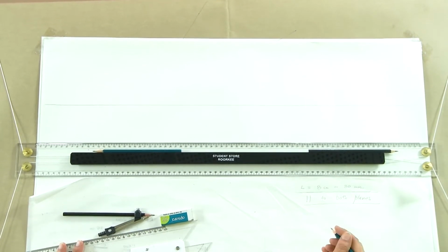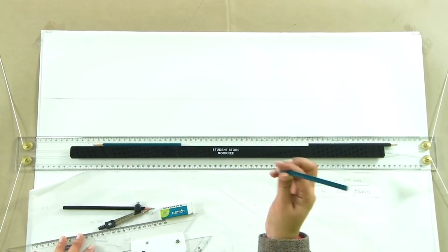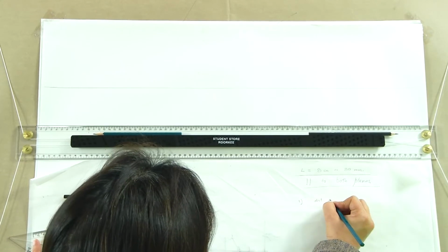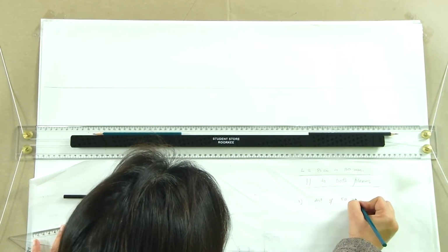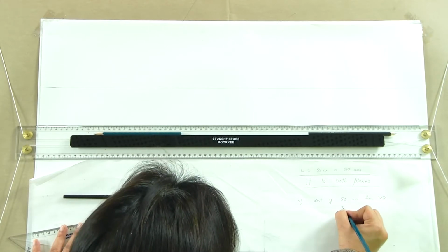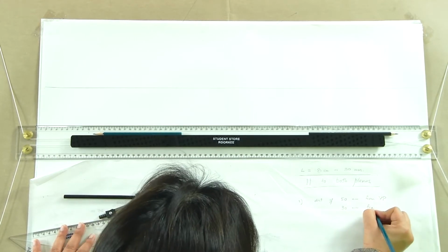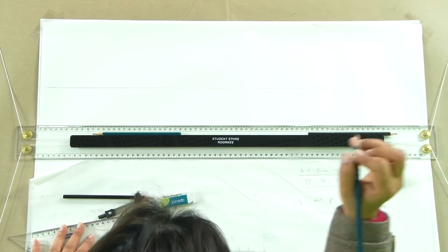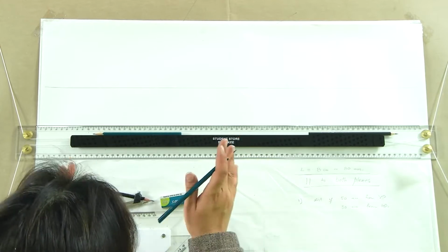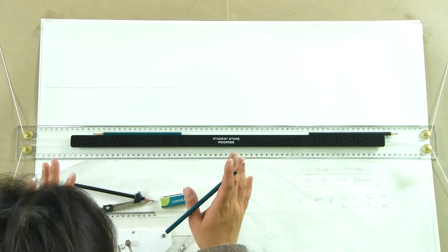So we are taking these two as the conditions, and other conditions we will assume to be changing. So in case 1, this parallel line is at a distance of 50 mm from VP and 30 mm from HP. Now, if a line is at 50 mm from VP, where would we see it?